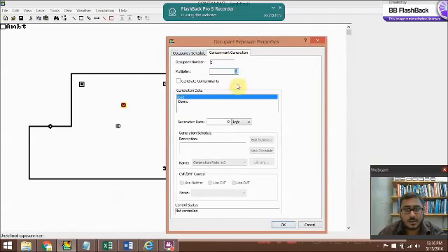Second is the contamination generation. So if they're generating CO2, just add generate contaminants, and then the addition of CO2 would be determined from the occupants. So it doesn't have a default rate of CO2 emissions from people. You have to specify that based on your activity or based on how many people. So that would differ based on what activity they are doing.